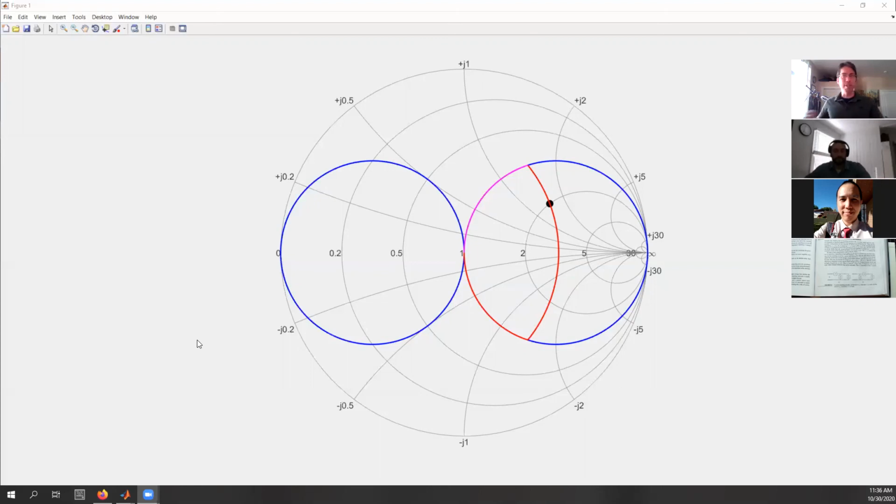And that will still work very well upwards of 2 to 3 gigahertz if you do nice thin little traces. But at 2 gigahertz, capacitors and inductors really don't act like capacitors and inductors anymore. All the parasitics buried inside the device start really causing issues. So I thought that was a good point.